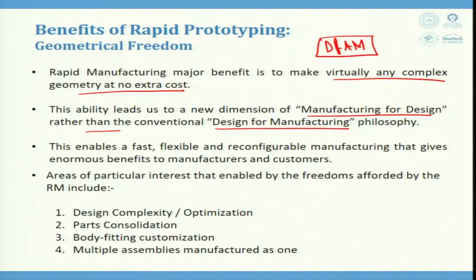There are certain terms when I talk about DFAM. One is infill of the material. Infill is when I am trying to build a solid component, it is not a 100% solid component, there are certain voids in it. So, what should be the void density? It could vary: if 90% of the material is filled, 10% could be void, we say 90% infill. If we say 80% infill, 20% of the voids are there. Similarly, we have density.